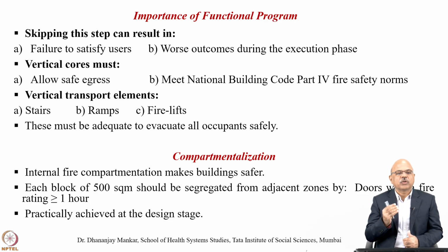Vertical egress must allow safe exit and meet National Building Code Part 4 fire safety norms, which is very important. Vertical transport elements like stairs, ramps, and fire lifts must be adequate to evacuate all occupants safely when a hazard happens.